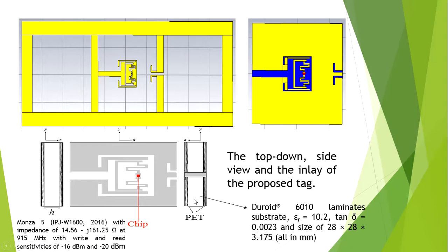And this is from the top view, and this is from the side view. From the top view, the white color part is the substrate, the gray color part is the copper part, and the line part is the PET. From here I'm using the PET double-sided substrate. The double-sided is actually a copper part. So we etch away the unwanted copper part so that this structure is obtained. We can see the substrate shown here, and the copper part shown here.